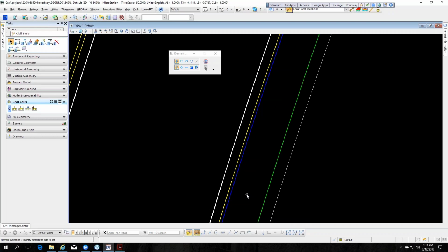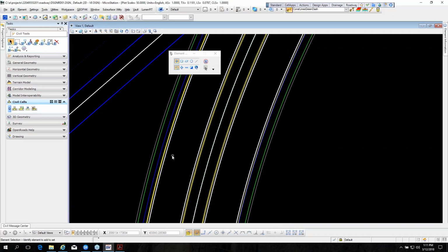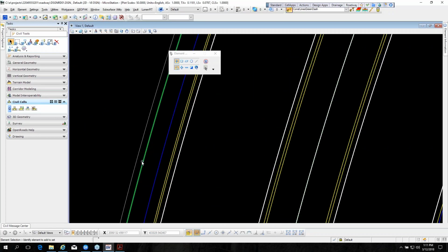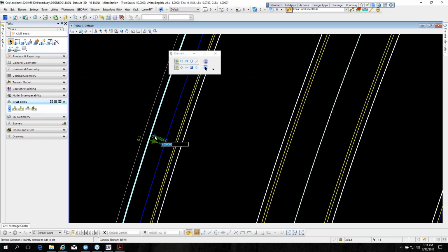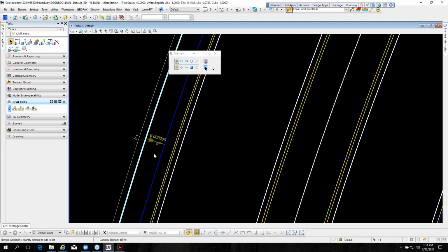That's confusing. Yeah, it is. I think it's going to strip out of it. So that's getting that utility strip out of there. So do the same thing for the other side. The back of sidewalk needs to be 6, and then the 3 down to 0.